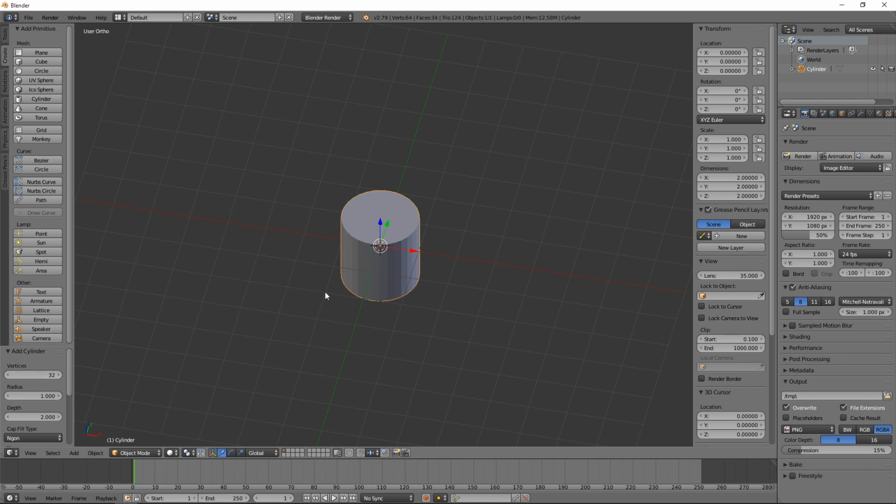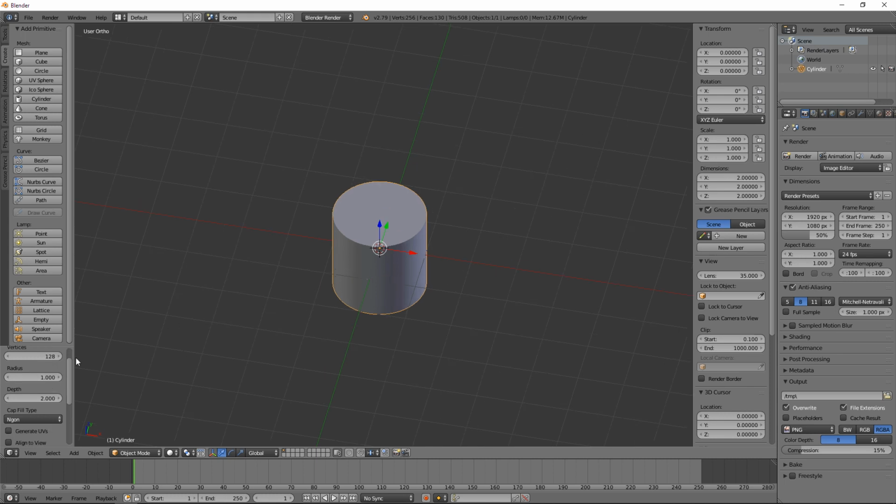In the 3D world, we can smooth it out in post-production, but in the printing world, you really need to give yourself some vertexes to work with. You can't change that after you leave this menu without some difficulty, so make sure you do that. The other thing is that you are adding it as radius. It is 1 Blender unit radius, which over here in the dimensions is 2. It's 2 from edge to edge, the full diameter across the whole thing. The radius is 1. That's important.